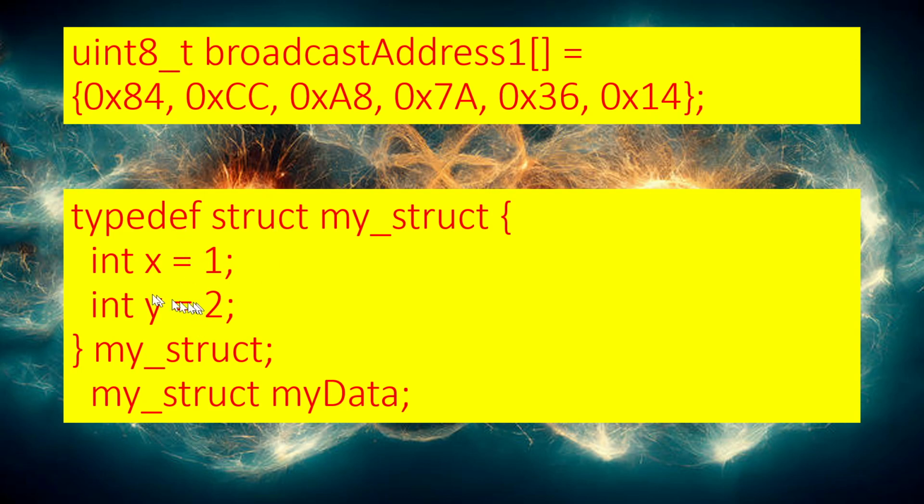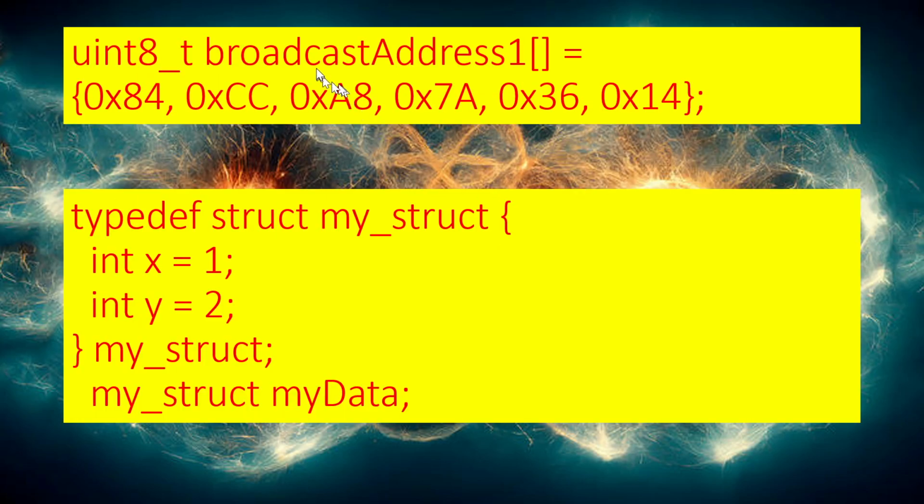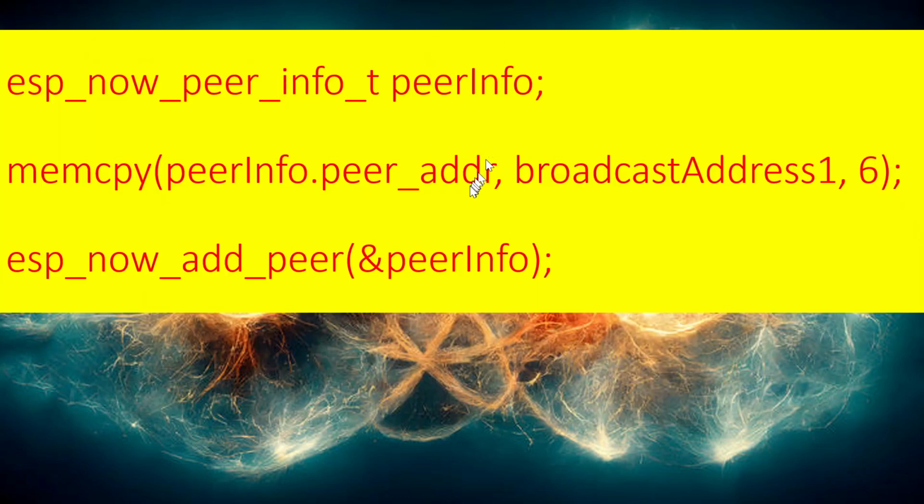So this is again the structure. On the sender side, I have just defined the values. Values can be reassigned, but for simplicity, because this is the minimal code, I have defined the values right in the structure. And then I will define peerInfo. Just use this line and just use this line. And if you recall, this was broadcastAddress1, so I have used it here, broadcastAddress1. And then I have to add my peer. So these are the setup commands.